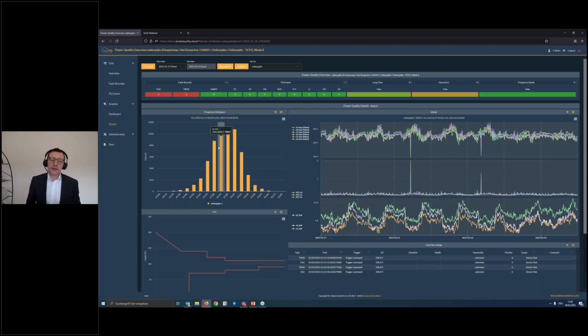But the point is, our devices continuously monitor the power quality in a really tough and fast way, with really high accuracy, up to 40 kilohertz, with a special supraharmonic feature which we provide in our devices. So if we have the medium average intervals of 10 minutes for the voltage and the voltage evaluation according to all the power quality standards which I have mentioned today, I also need the information how the voltage was in the mean, min and max value, and not only for the voltages.